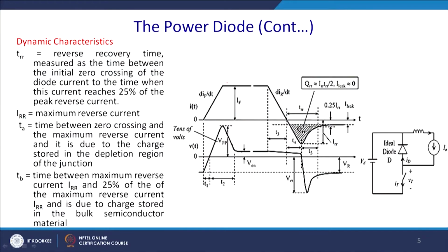So, what happens when a voltage builds up, current also builds up, and there is a rate of change of the forward current, and that will peak up. In this region you can see that the voltage is building up and the current is also building up, because it has a junction capacitance. So, in this region the diode will give you a voltage drop and power drop across the diode, that is called the turn-on loss of the diode.